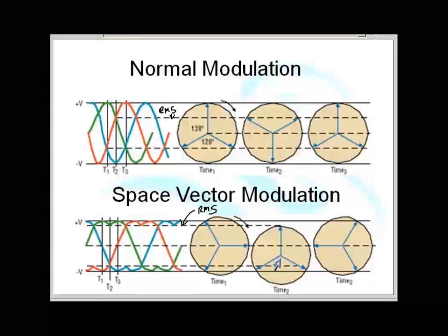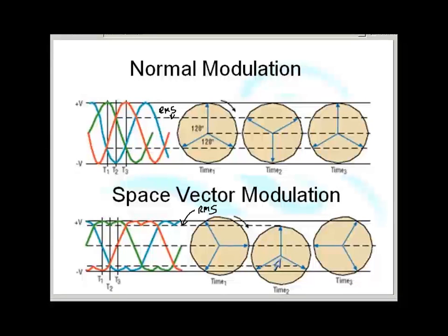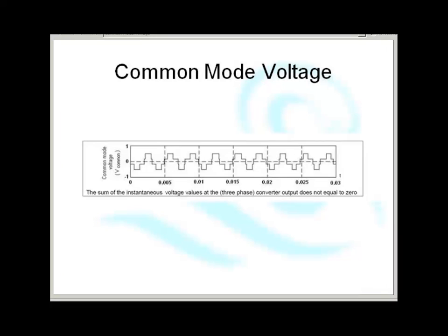What's happening is we've got a slight neutral voltage, 2 or 3 volts. Whatever you get in the coil, of course, you also get in the rotor. So now we've got a slight center point voltage in the rotor. It's called a common mode voltage. What we've got is a very slight common mode voltage inside the rotor.